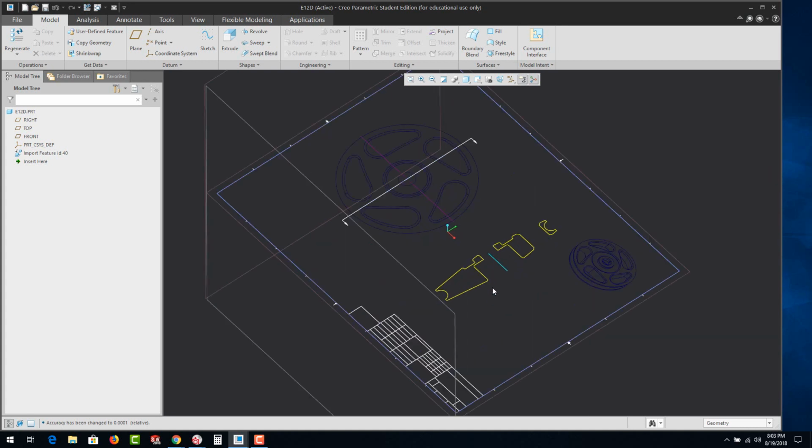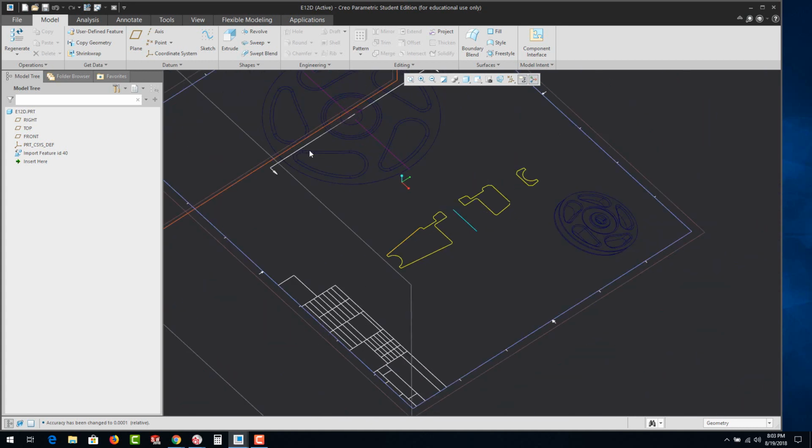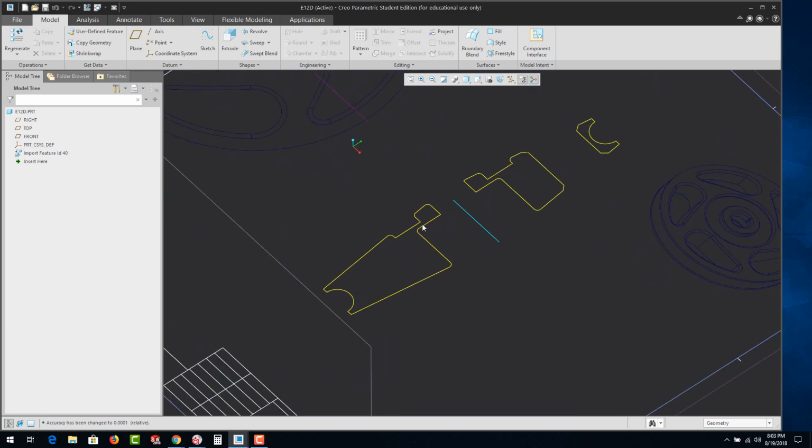Okay, now I'm going to go ahead and zoom up here. We could see that what we have here is actually a cross-section of this wheel. And the cross-section views are great when it's a circular object. Hence, you could actually take this geometry and revolve it 360 degrees. And we already have a center line in there. Actually, we're going to have to copy some of this geometry, and then we'll go and spin it around with the revolve. However, there's different strategies that sometimes work better than others.